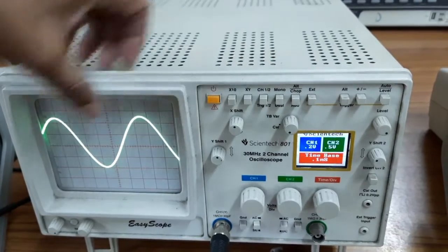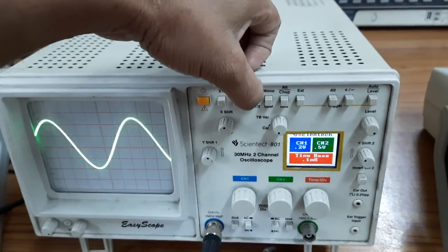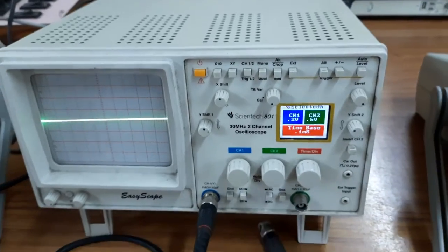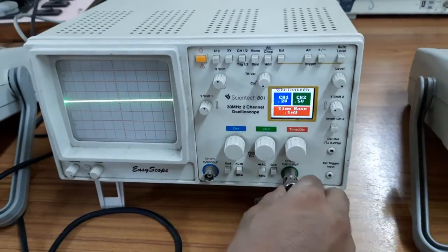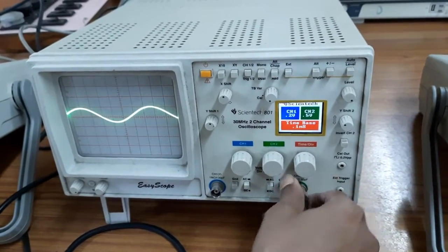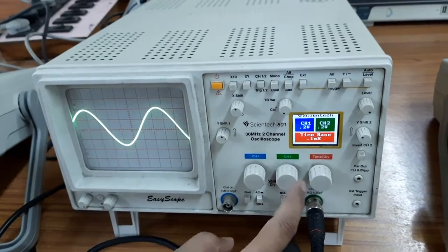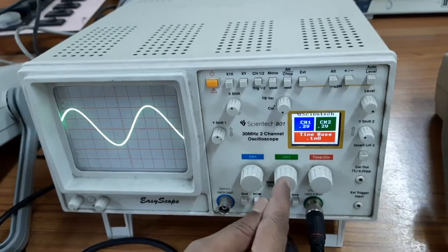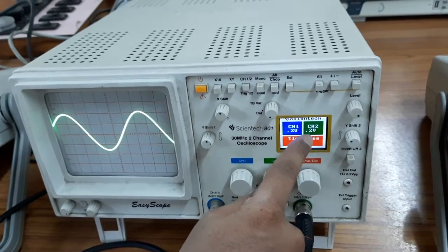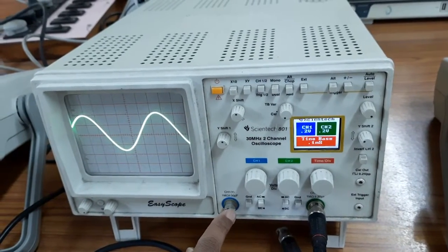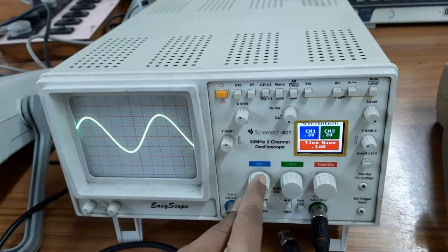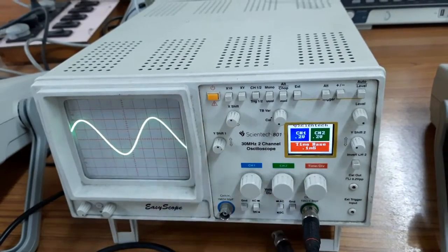Here it is written channel 1/2. When it is open, it shows channel 1. If it is pressed, it shows channel 2. Nothing is connected now. If we connect in channel 2, we can obtain our signal again. That is the signal in channel 2. When it is connected in channel 2, we have to vary this volt per division and follow this reading, this green color. And when it was in channel 1, we vary this blue one and get the blue reading. Clear?